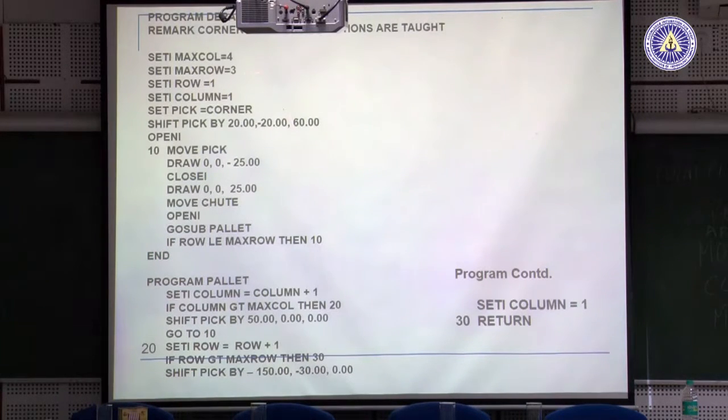Now if I change this number, the same program will run for any indexing. So the idea of writing programs today is by making very, very small subprograms which you can integrate and just call whenever you like. So the same robot can do different things at different times without changing the main program. And the language is very, very simple. I think anybody can write, but you have to be a little careful.